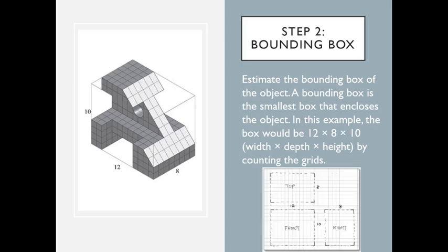The views of the box will be rectangles. Sketch the rectangles with correct alignments and fit the paper nicely. Then, sketch the details of each view using the rectangles as guidelines.